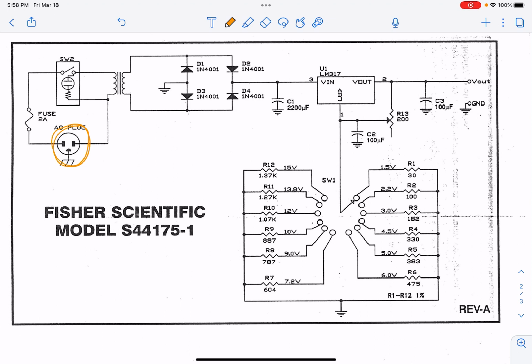This is the three-pronged outlet that you would plug into an outlet, the three-pronged cord. This symbol right there that kind of looks like a rake or something is the symbol for grounding when what you're grounding is the chassis or the blue metal box. If there was a frayed wire and some of the electricity could go through the blue metal box, it would go into the ground right here rather than through you. Because if the electricity goes through you, you hate it when that happens.